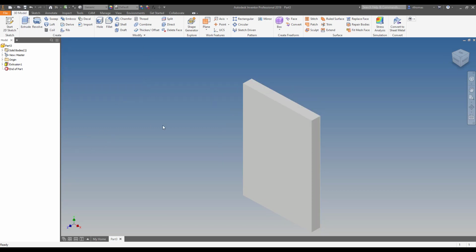So we've now created our first solid part feature. So what's happened now? That sketch 1 has disappeared. Well, it hasn't actually disappeared. If you see, there's an arrow. And remember from before, if there's an arrow there, it means there's something underneath it. And sketch 1 is now underneath extrusion number 1. They're now inherently linked. So I'm just going to minimize that again.